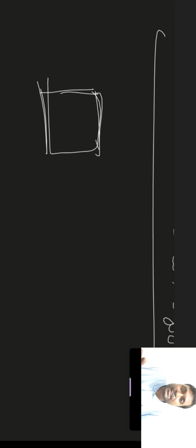So to obtain different types of fits, like clearance fit, interference fit and transition fit, three types of fits, we will vary the dimension on the shaft. We have manufactured holes which will vary between two dimensions, lower limit and upper limit.